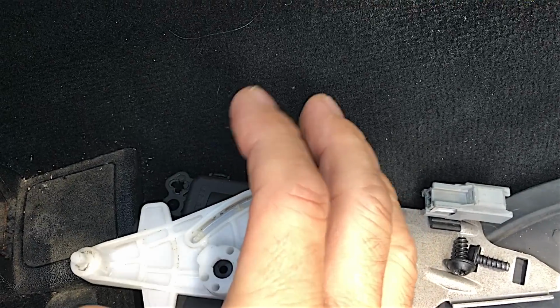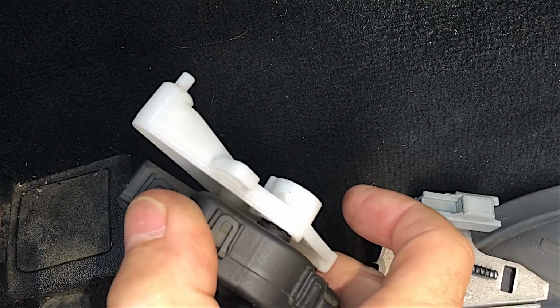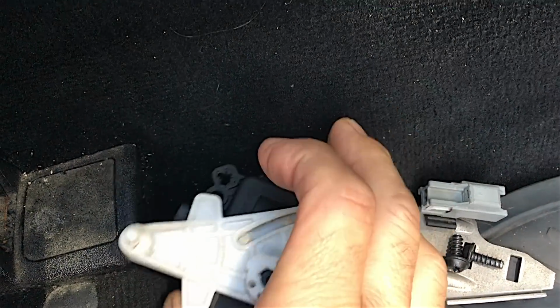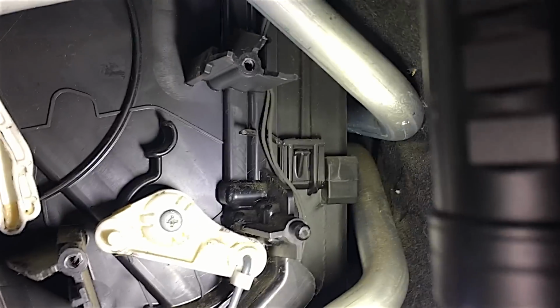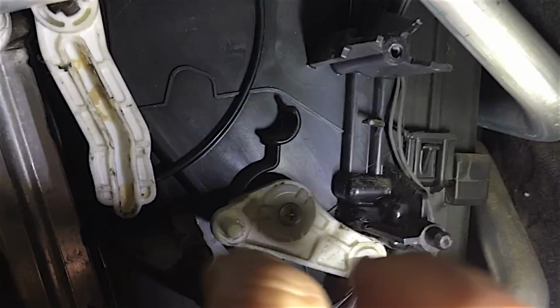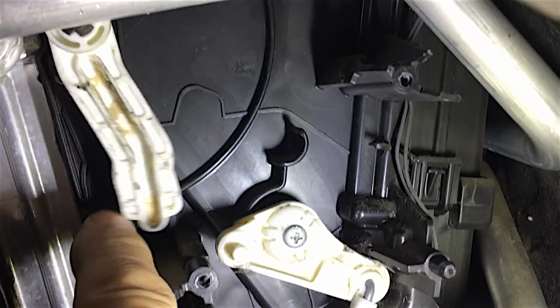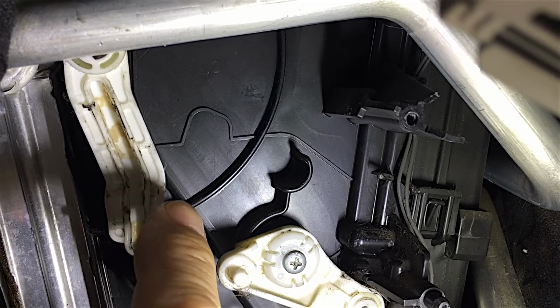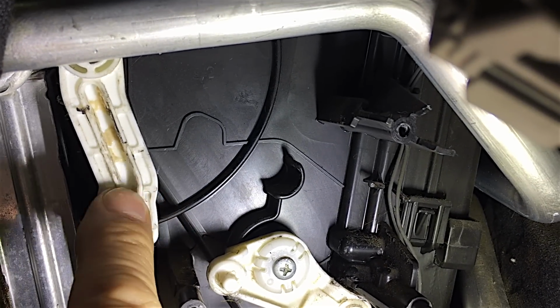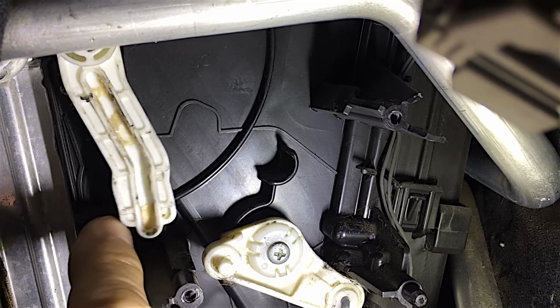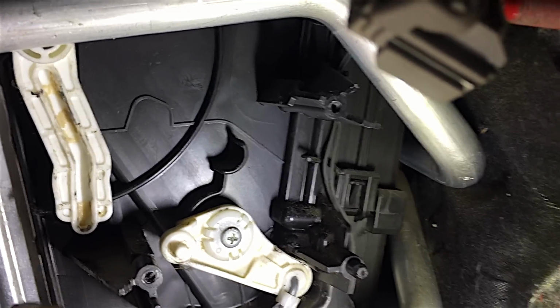But this other lever might not be in the right place, so I guess it's possible that you could put this on and miss this other lever. So I'm just going to try and show it in here. There's the first one, there's the pin there, and this one here, see that, that's another lever doing a flap as well. So make sure that the pin on that motor dogs into the groove in this lever when you're refitting that, and hopefully that will be it. You won't have any problems after that.